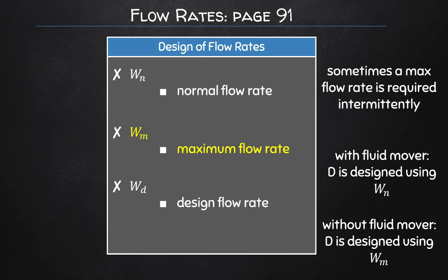So this is a good example of managing different flow rates, a normal flow rate that is generally expected and one that exceeds this normal flow rate in only short intervals, where you have 10,000 liters per minute leaving the digester, so that you can discharge it quickly, and therefore you can then fill the digester up again quickly and limit the time between batches.